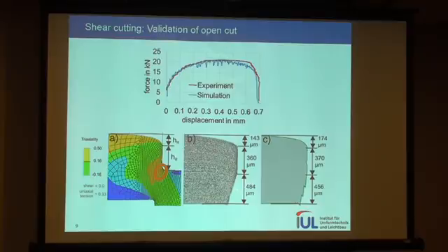So I decided to use the triaxiality to identify whether we have burnish or fracture. You know that shear loads usually have a triaxiality of about 0, and uniaxial tension has a triaxiality of roughly 0.33, and assuming that fracture occurs under tensile load, you can say that if tensile loads become dominant in this region, fracture occurs.